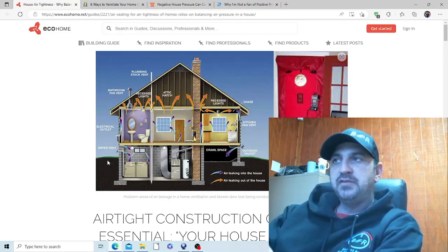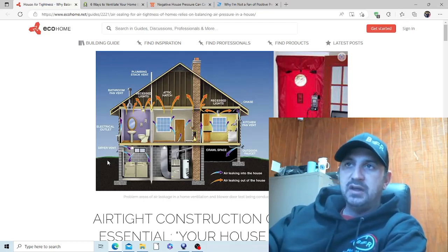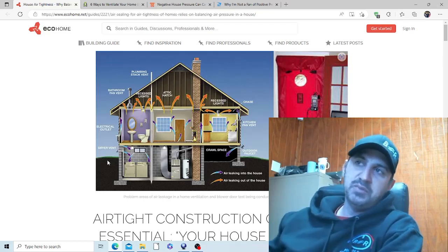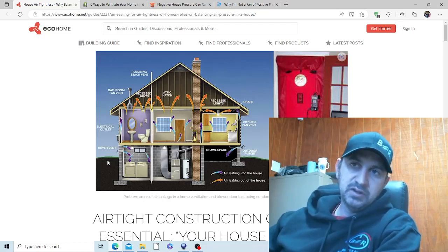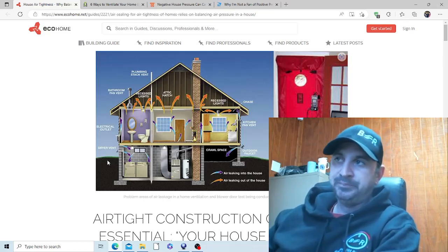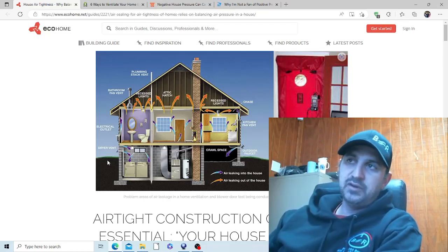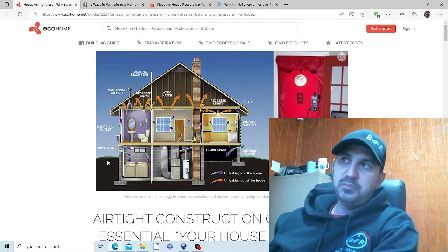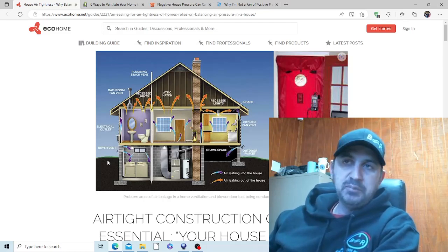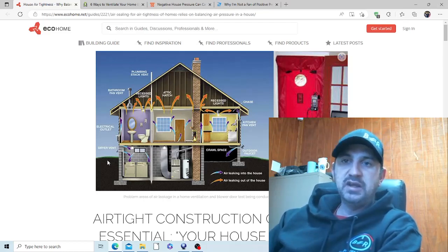And then upgrading from the sheathing, there's a thing called the ZIP System, and it's sheathing with insulation that's made to make a tighter home, and then they have some tapes and caulks and sealants that you can use on it to seal it even further. We're not going to get into that in depth, but if I was a builder, I would be looking into it. It's a really cool system, really helps minimize any air exchange.